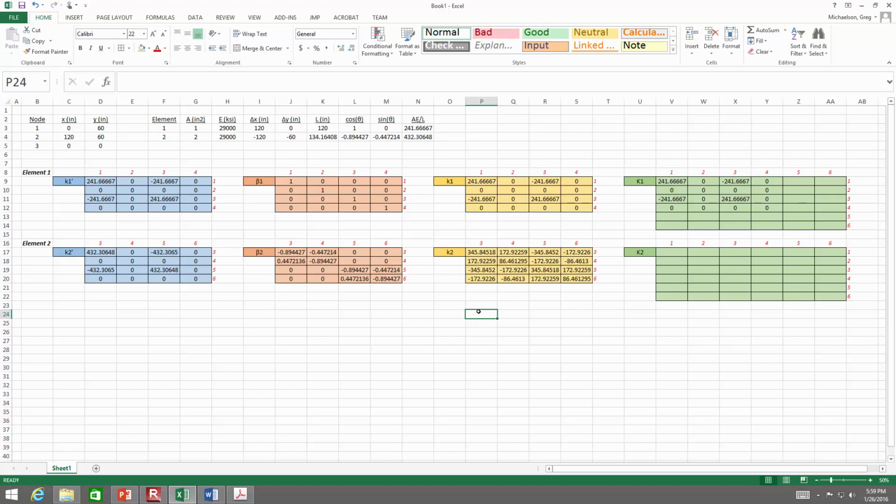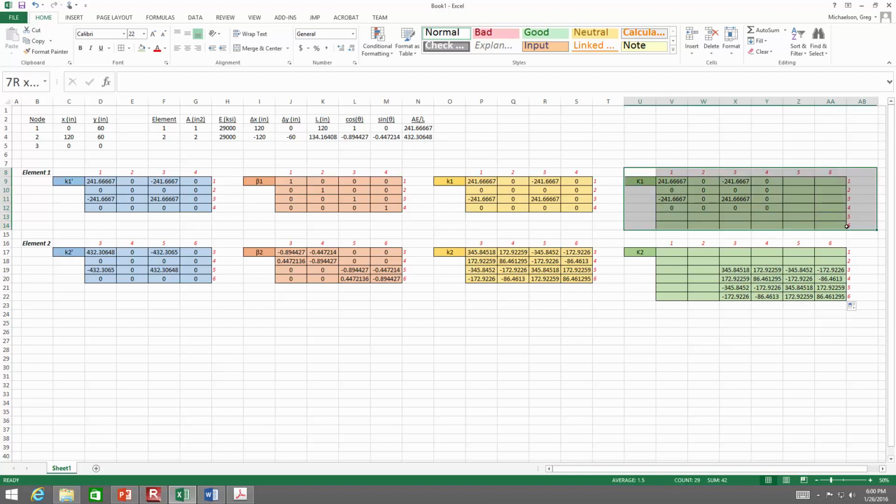Now some of you have already gone ahead, and that's fine. Those terms are going to populate right here, aren't they? In this lower right coordinate, because 3, 4, 5, 6, 3, 4, 5, 6. So they belong right here. So I'm just going to grab here and say equals that. Everybody see that? So what do I do if I'm assembling and I have overlapping terms? I add them together. So this is the assembled stiffness matrix for element number 1 right here.